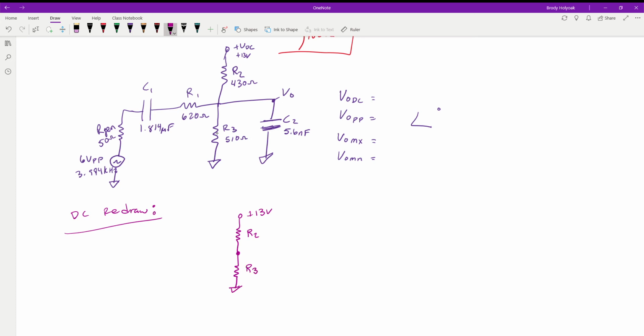And then coming off of that branch, we have a capacitor. But remember, a capacitor is essentially an open to DC. We're going to assume this thing's been on. We're not worrying about the charging constants, anything like that. It's on, it's running. The capacitor has had the time it needs to charge. So we're not trying to figure that out. This is after it's said and done. So once we do that, we essentially have an open from there over to here.